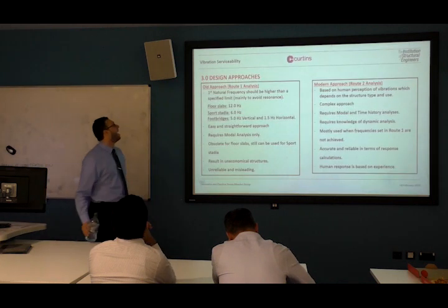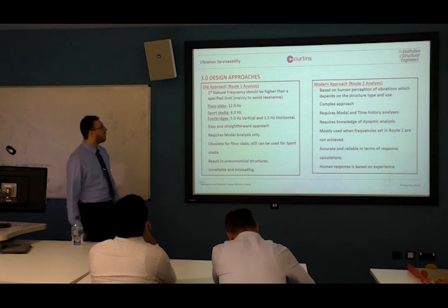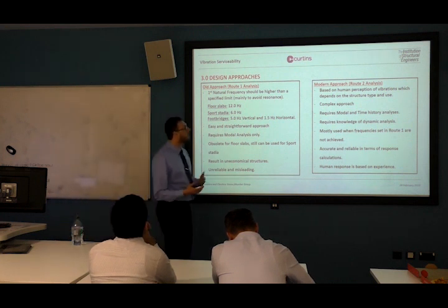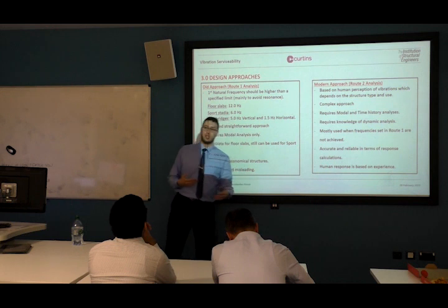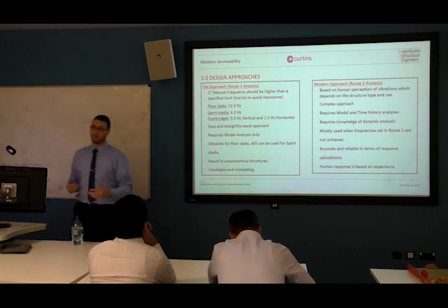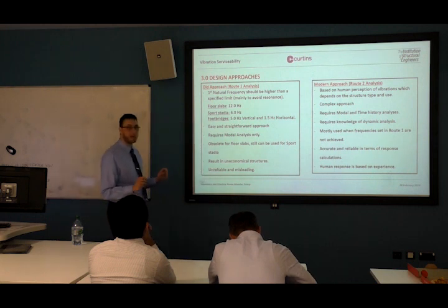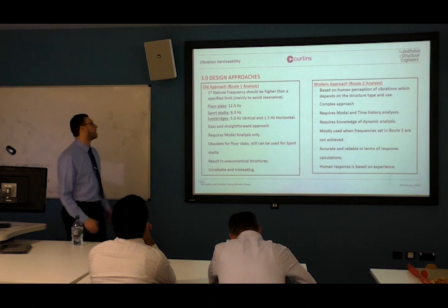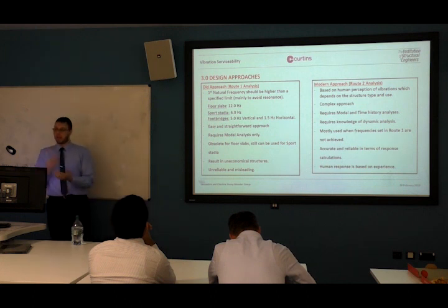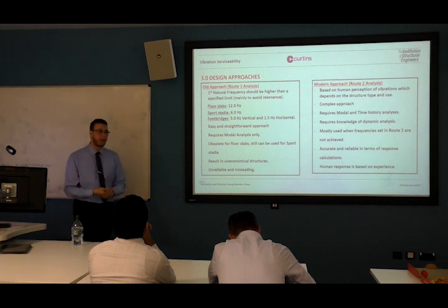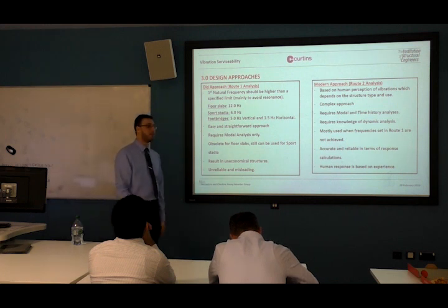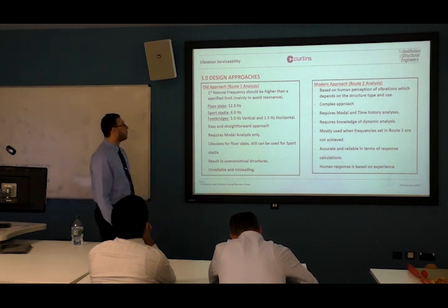All right. So now I'll speak about what difference we have in the design approaches for vibration serviceability. Starting with the old approach, I'll call it Route 1 approach or Route 1 analysis. And Route 1 analysis is very simple actually. Just design the structure to avoid any resonance. That's it.